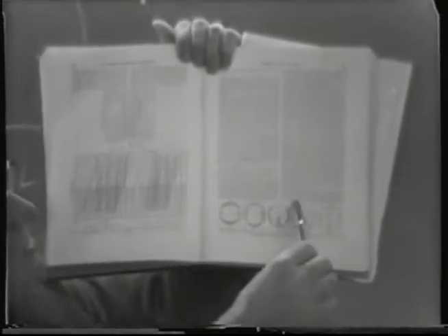And there's another arrangement here, shown with 6 tubes around the perimeter and 1 large tube in the middle. So for one tray, you'd have the overflow in 1 large tube in the middle, spread out radially to the 6 smaller tubes and flow down to the tray below, and then those would flow back into the larger tube in the next tray below.